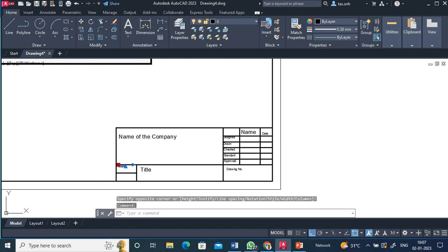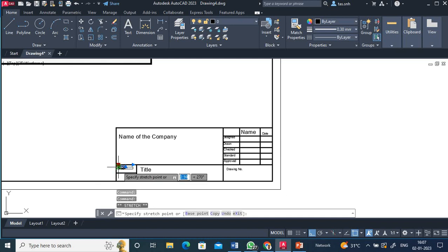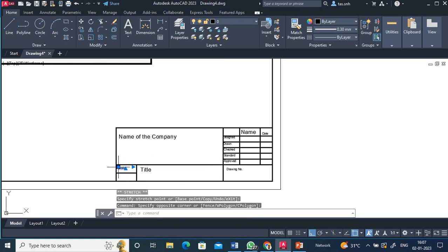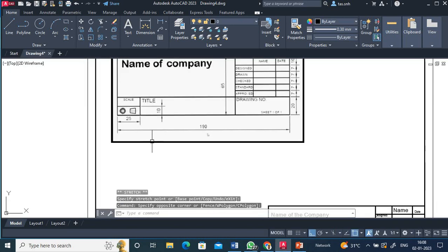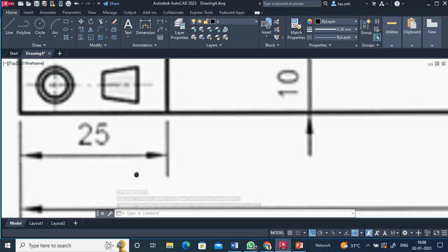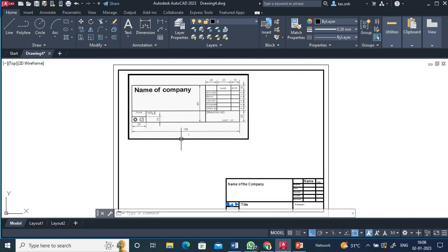If you want to pull it down, you can use this sort of cursor. Okay, when you click it, this square will be shown. So using that square, if you click it, you can pull wherever you want. Then the symbol. For drawing, the symbol has a meaning. It is the symbol for third angle projection. 2 concentric circles will come, and then a parallelogram like thing. This represents a frustum of a cone. So that symbol we are going to draw now.